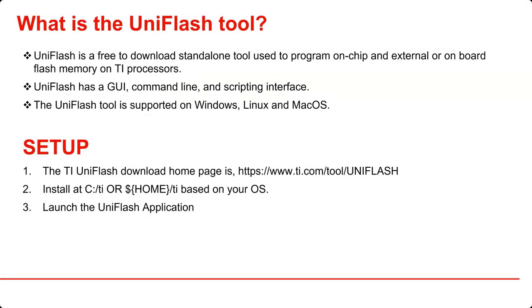Uniflash is a standalone tool used to program on-chip, external, or onboard flash memory on TI processors. The Uniflash tool supports GUI, command line, and a scripting interface. The tool is supported on Windows, Mac OS, and Linux and is free to download.